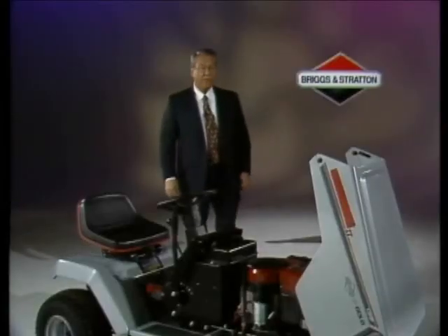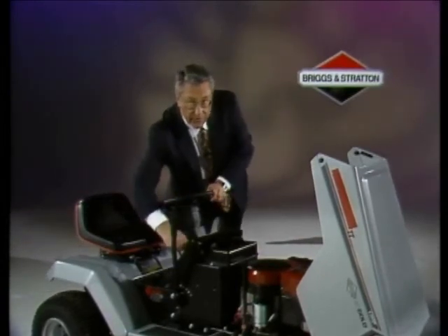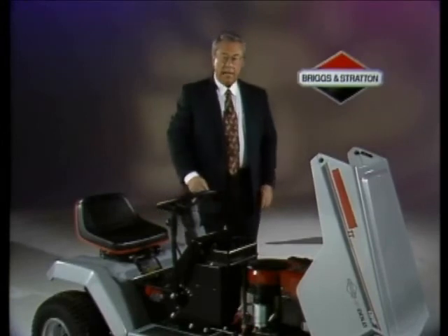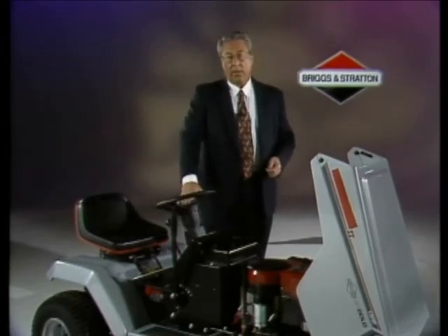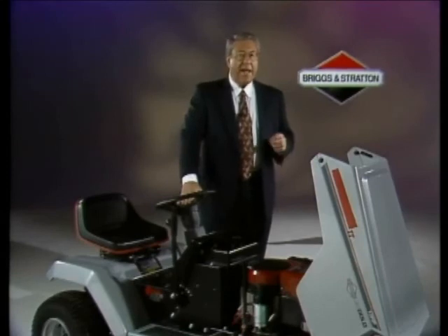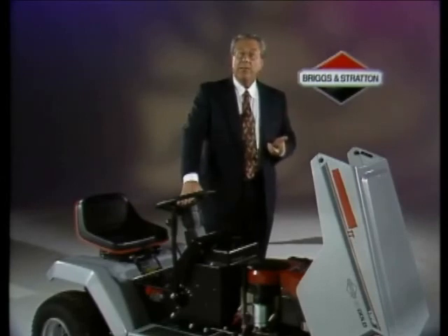Now, let's look at one more relatively new component of modern carburetors. We've all heard the awful sound of afterfire that sometimes occurs a few seconds after an engine is turned off. Even though the ignition's off, most of the physical principles that make the engine work are still operating. As the engine slows, the governor responds by opening the throttle plate wide. Fuel flow continues even though the ignition has been shut off. The result can be afterfire.